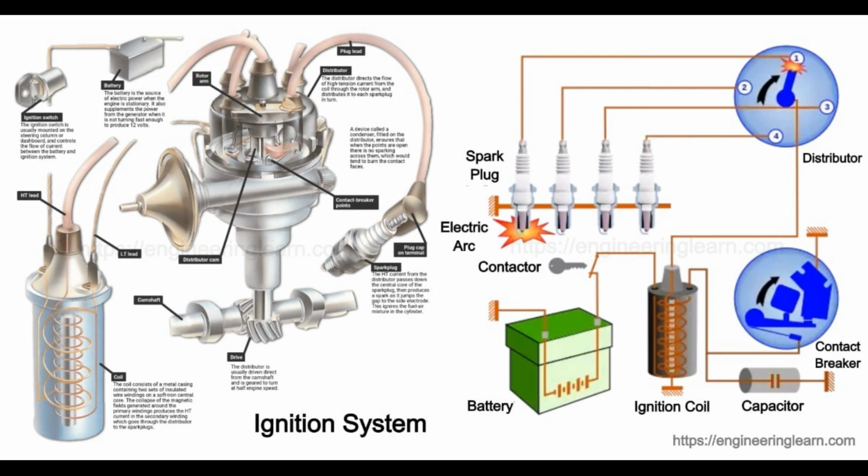Low maintenance cost. Disadvantages: in the battery ignition system, the battery is necessary for the ignition. It becomes difficult to start the engine when the battery is discharged. Occupies large space. The efficiency of the system decreases as the engine speed increases. Since the breaker contact points are continuously subjected to mechanical as well as electrical wear, this results in short maintenance intervals.